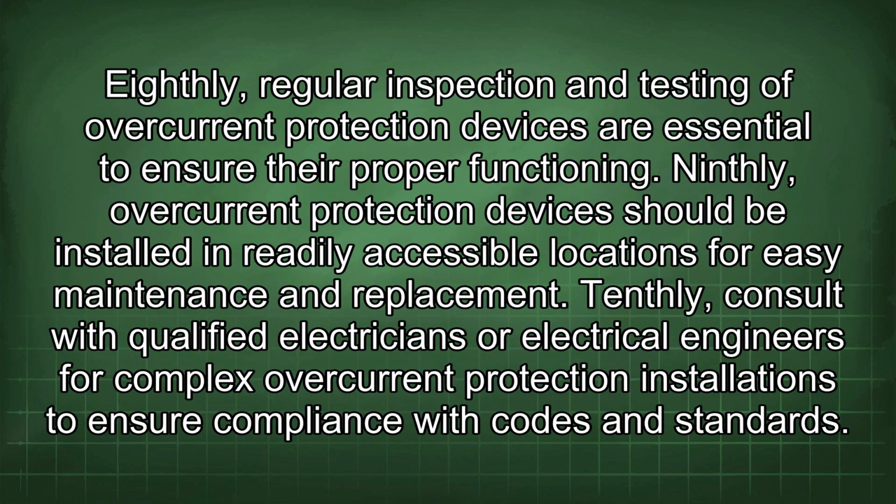Eighthly, regular inspection and testing of overcurrent protection devices are essential to ensure their proper functioning. Ninthly, overcurrent protection devices should be installed in readily accessible locations for easy maintenance and replacement. Tenthly, consult with qualified electricians or electrical engineers for complex overcurrent protection installations to ensure compliance with codes and standards.